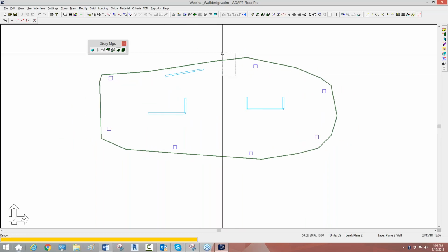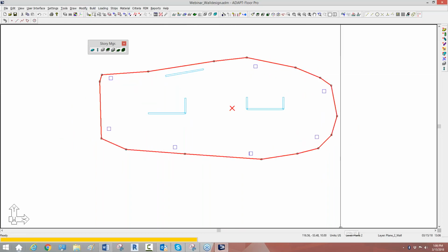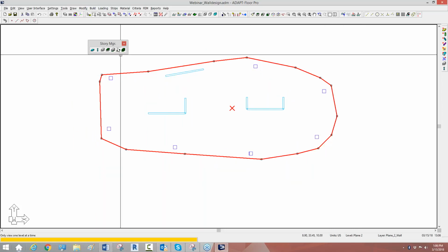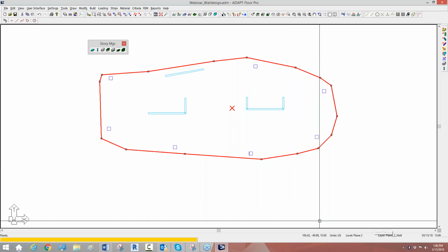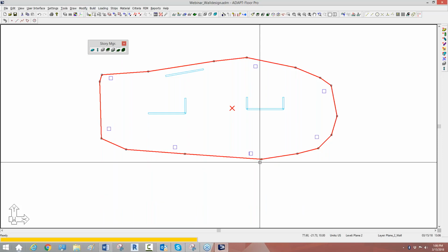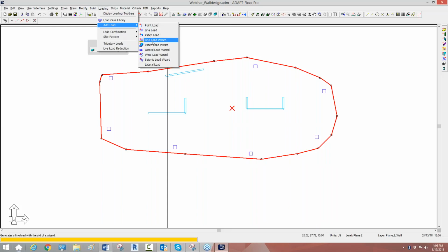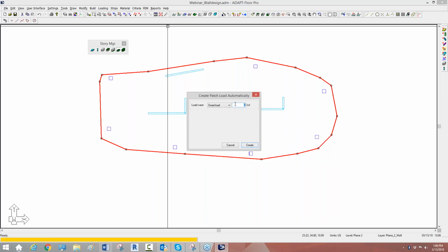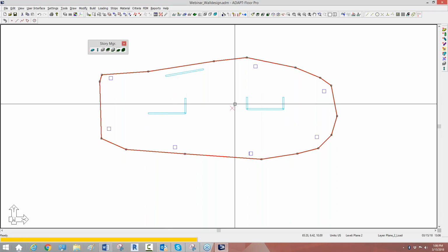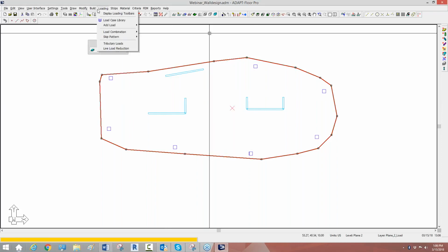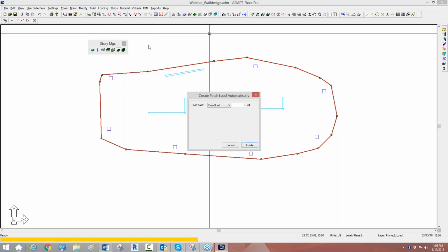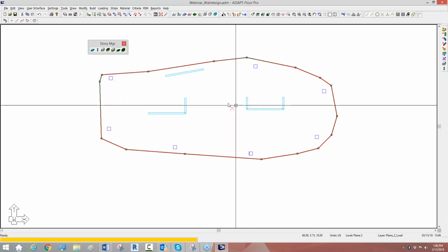And I'll go ahead and just add load to this base slab. So this is the first elevated slab that I'm working on. You can see here I'm working in single level mode, and we're working on plane 2. So all of the modeling and modifications I'm making apply to the current plane. And we'll add just some basic gravity load for dead and live. So this is superimposed dead, we'll say is 20 PSF, and superimposed live, we'll go ahead and use, let's say, 50 PSF.